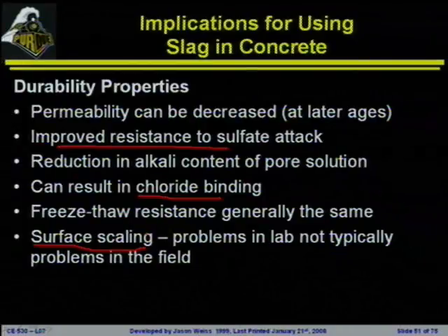If you go out in front of the civil engineering building, you'll notice that it looks like somebody exposed all the aggregates for that 100-foot strip on the mall as you walk down on what is the front side of the building, but the back side of what everybody approaches. You'll notice that the aggregate surfaces all look like they're polished. That is a scaled surface. The Portland cement covering that was on top of them came off with de-icers.